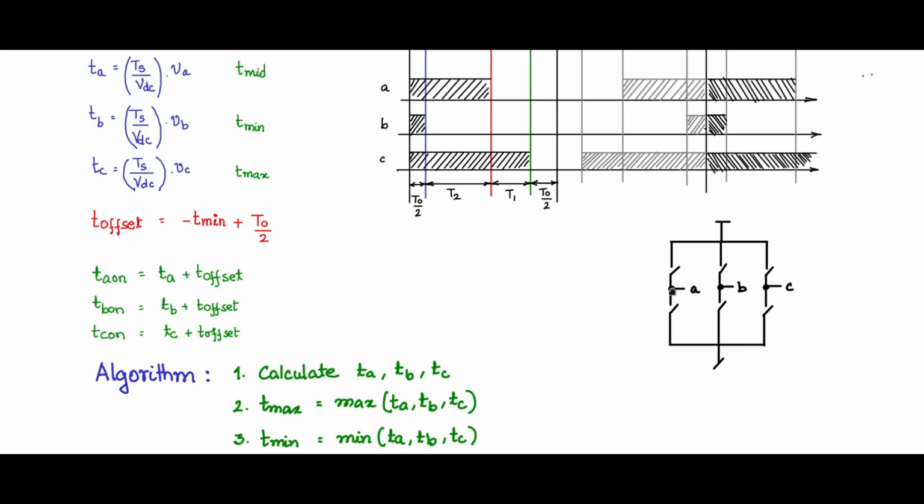So here, for every arm, for the top switch and the bottom switch, you will give A and A bar, but you don't just give an inversion of A to the other device. One you will give A, other you will give A bar. It's not just a plain inversion.